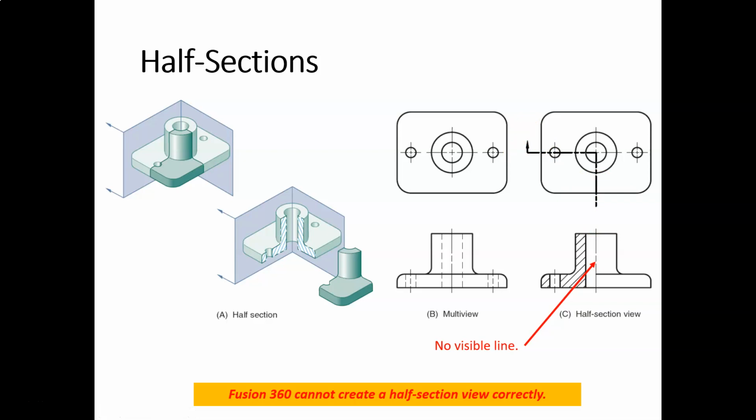True story: at MIT, Massachusetts Institute of Technology, a world-renowned engineering university, they have wrong images of half sections up on their website with an arrow pointing here. That is completely wrong. In the standard for section views, the rule book developed by the American Society of Mechanical Engineers, they clearly state that this only has one arrow. So this is correct. What you see on MIT is wrong.